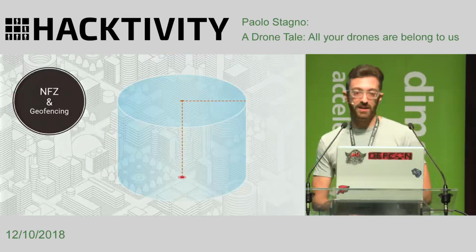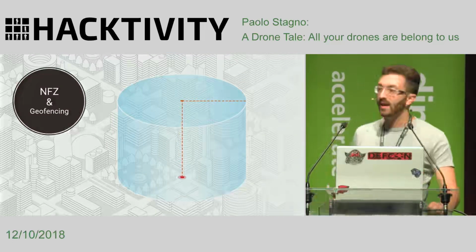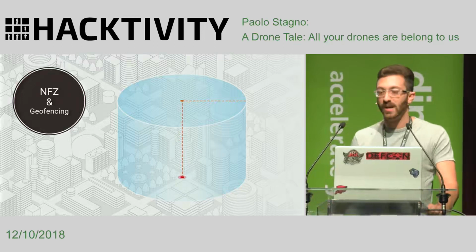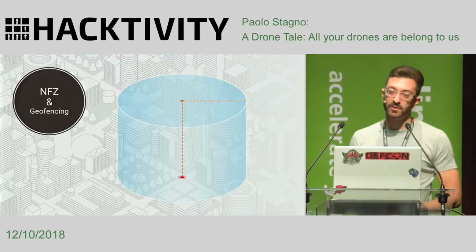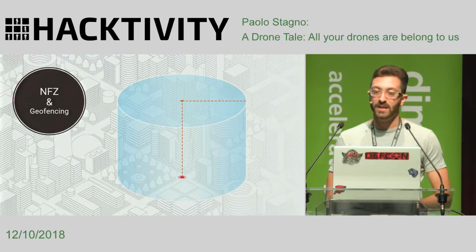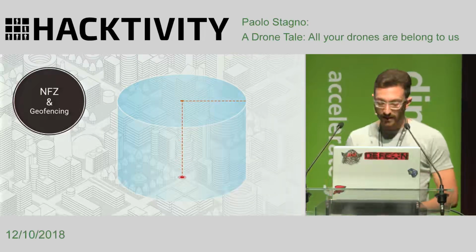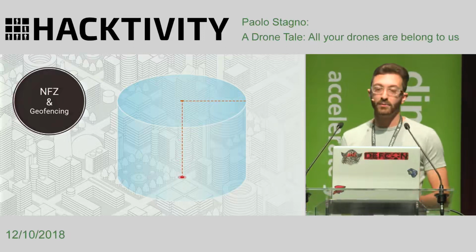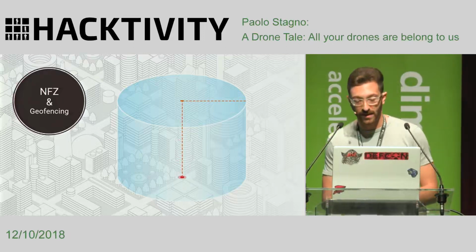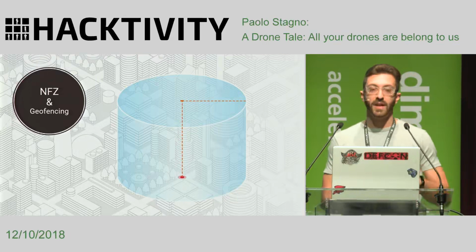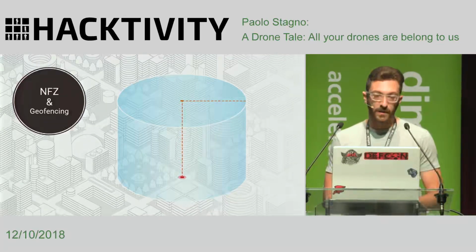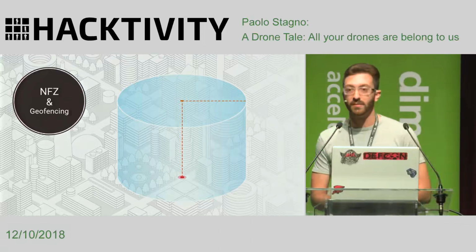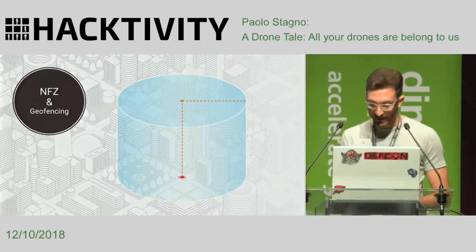So, here a small digression. In Phantom 3 models and later, DJI provides a geofencing system, or an inbuilt no-fly zone list. And the no-fly zones are, as shown by the image, some virtual fences with a specific diameter, which the drone cannot fly in. So this makes it possible to exclude some locations, like airports or military bases, from drone flight.